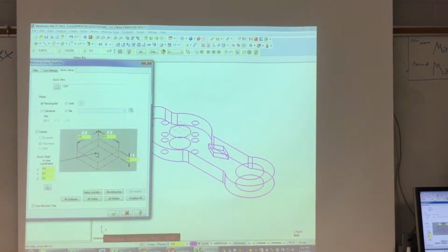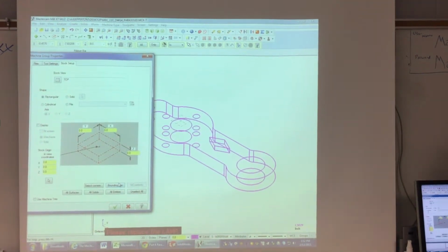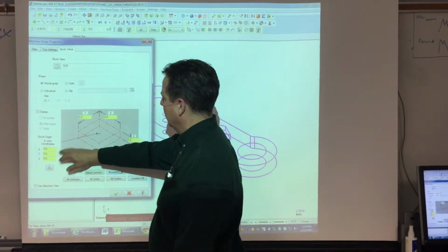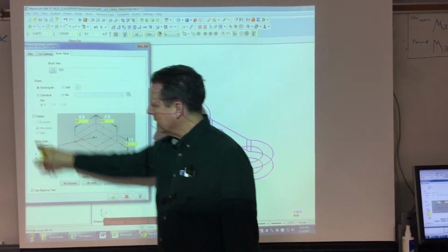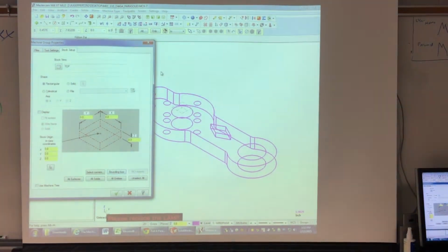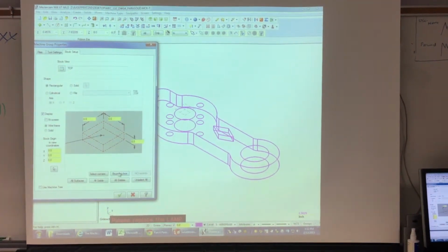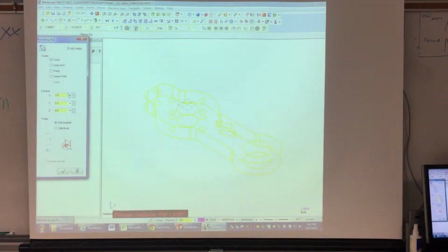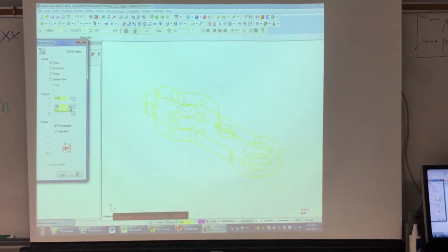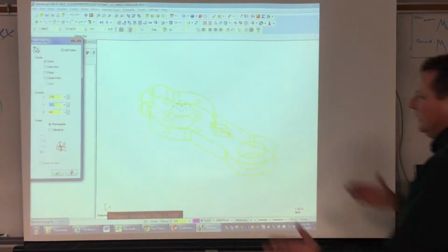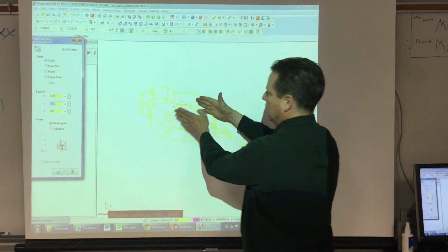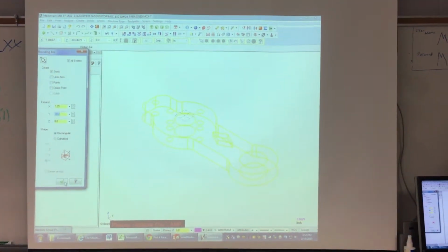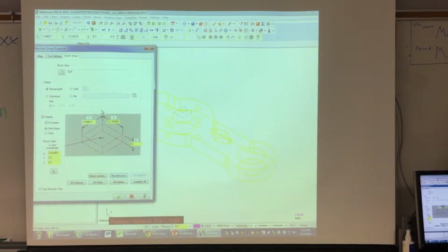Now that that's done, I can go to stock setup. And what I did here was I choose bounding box. I've got no stock anything in here. I have to make sure it displays. So I check display, and then down here, bounding box. It lights up the model. I'm going to expand X and Y lines. It's going to draw a box to it, but I'm going to expand it 1/4 inch in each direction. And then I get these numbers here.